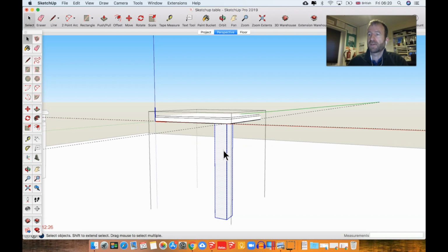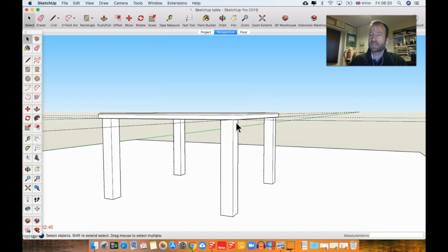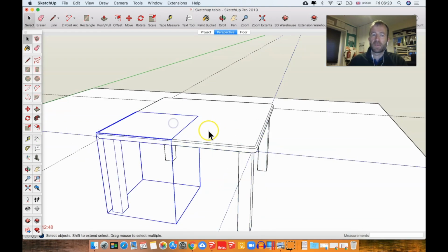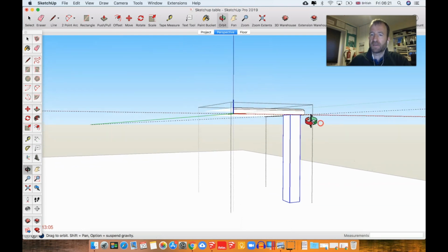Component will mean that if you copy it, it will be duplicated. So if I wanted to copy this within its sort of parent space that I'm now working within, and know that it would duplicate and changes to the first one would affect the second one, then I'd maybe want to make it a component. But because I know its copy exists within other parent components that are the same, it may as well be a group. I hope that's clear. So double clicking back in, triple clicking, make that a group, and then at this stage I'm going to add the apron.